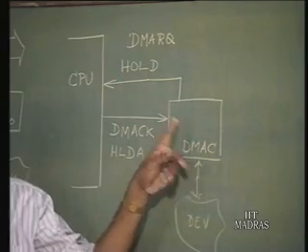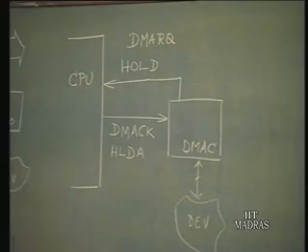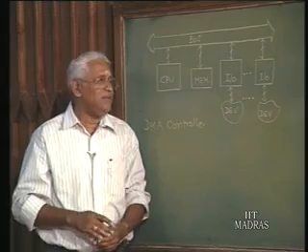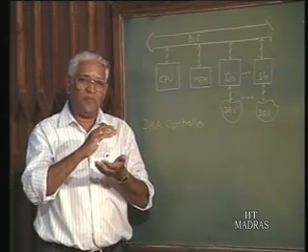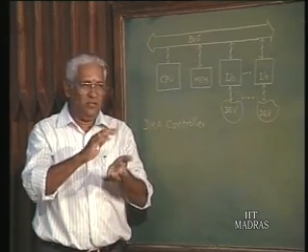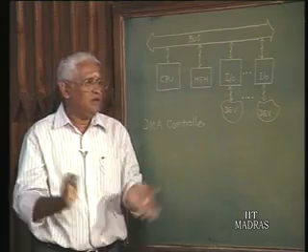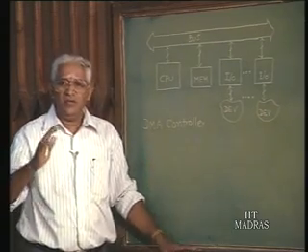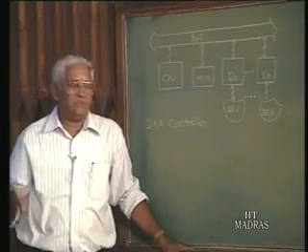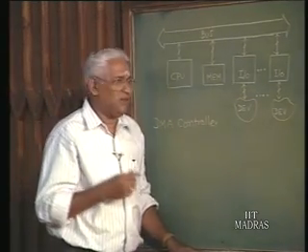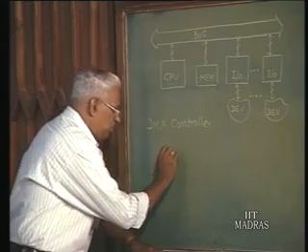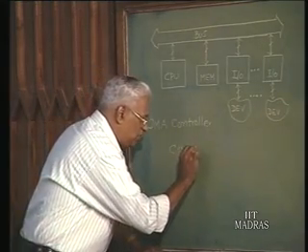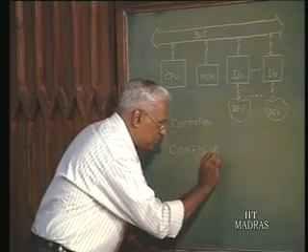But then the CPU, as the general master of the bus, must have indicated to the DMA controller earlier, okay, you can expect possibly 1 kilobyte of data or 10 kilobytes of data or whatever, and then when that comes, store it starting from say location 1000 or 10,000 or whatever it is, some address. Okay. So, this we have seen. So, essentially this particular device service routine is mostly during the configuration phase, is it not?